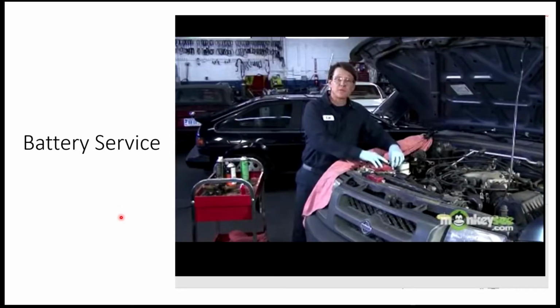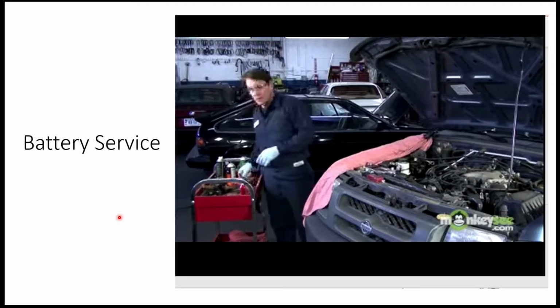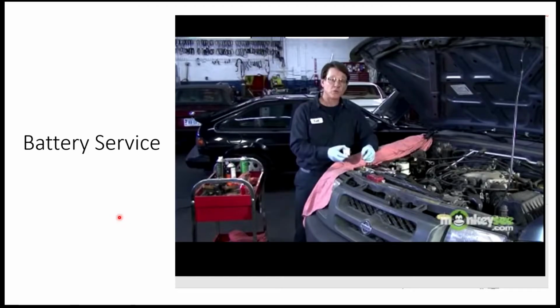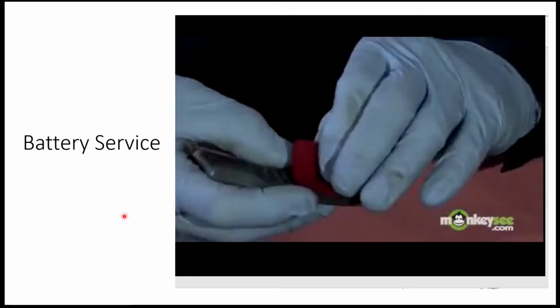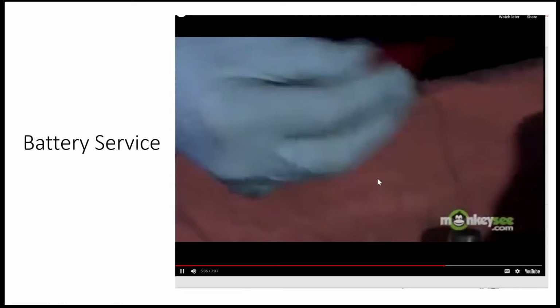If you noticed, I used rags underneath these battery terminals while I was cleaning them, just to make sure that none of the acid I removed from the cables drips down on any components in the car. You're wearing gloves and eyeglasses to prevent that from getting on you. You certainly don't want any of this getting onto any items on your car. Again, before installing, we're going to use battery terminal protectors. We've cleaned them, now we want to keep them that way. The red terminal, of course, is going to go on the positive post.